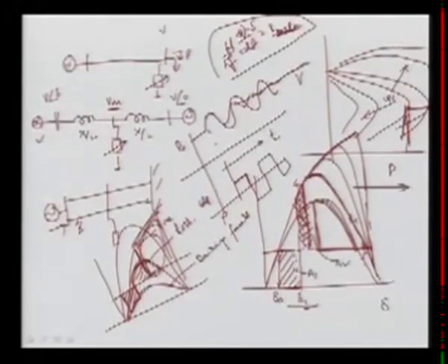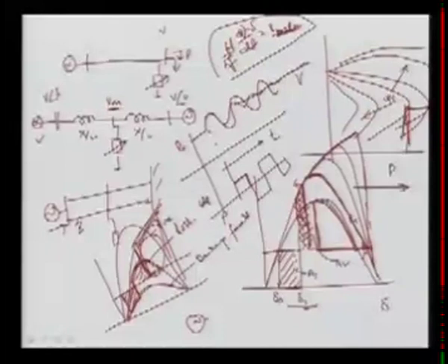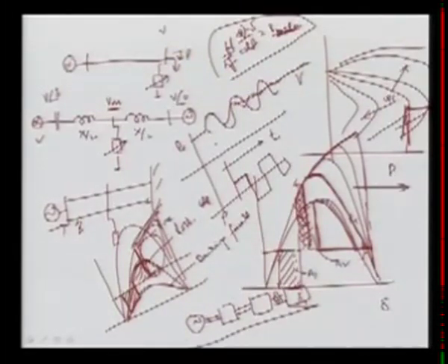Another point which I said is the natural frequency of the system. You know, here we are having the generator. This generator is rotated by the turbine with several stages. So we are having several natural frequencies of these systems. There may be a possibility these oscillations will interact with the natural frequency of the system, and huge oscillation will occur, and sometimes it may give chaos, and you can say damage of the equipment as well. So for the swings of the disturbed machine, we can put some reactive power compensation. In this way we can damp out the power system oscillation, and this is another advantage of your shunt compensation.